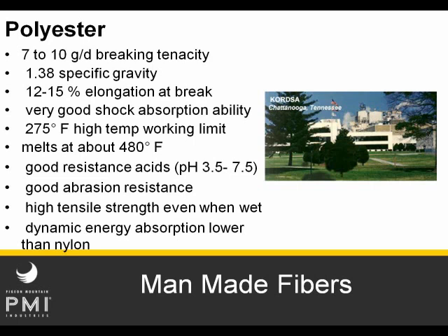In either case, the rope has to be exposed to incredibly high concentrations for very long periods of time, or it has to be exposed to intense heat at the same time of the chemical exposure in order for the deterioration of the fiber to be very significant. In fact, the exposure limits that would destroy the integrity of a life safety rope are so intense that the user using the rope wouldn't be very happy either. That said, any rope that is subjected to any significant chemical contamination should be retired as soon as possible.